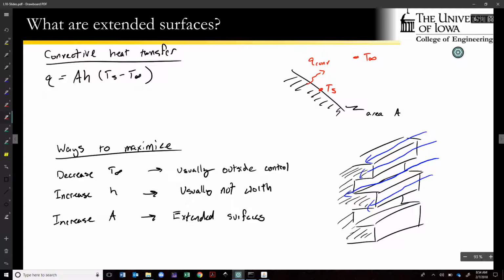we can get a net increase in the amount of convection out. But the mechanics of this are a little bit complicated. So far we've been talking about one-dimensional conduction. Heat goes in one direction through the solid and it leaves through some surface. As soon as you introduce this sort of complication to the geometry, conduction is causing a diffusion of heat inside of the solid, and outside we've got heat being convected away from every exposed surface.